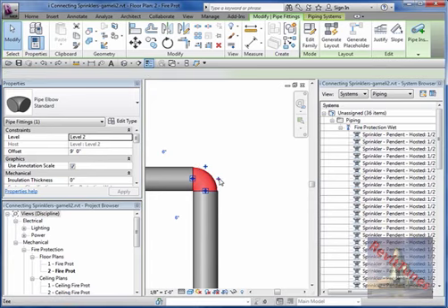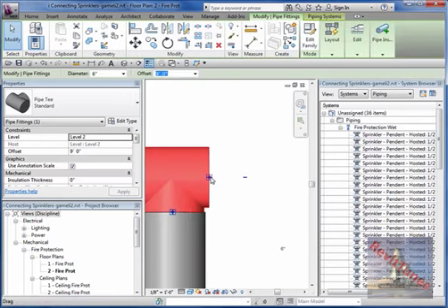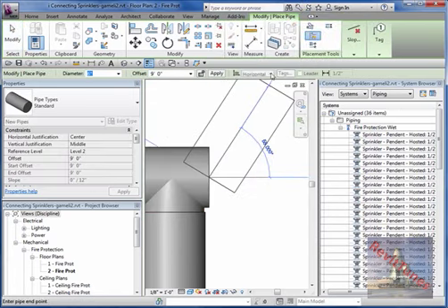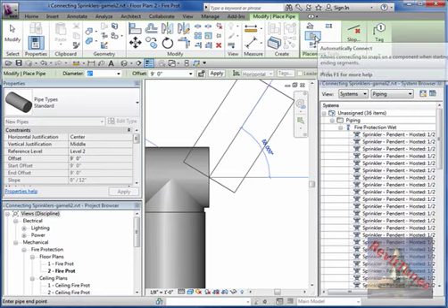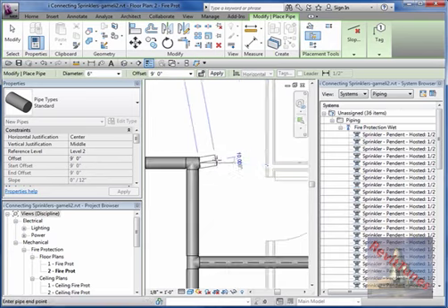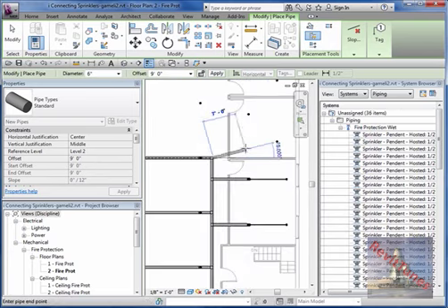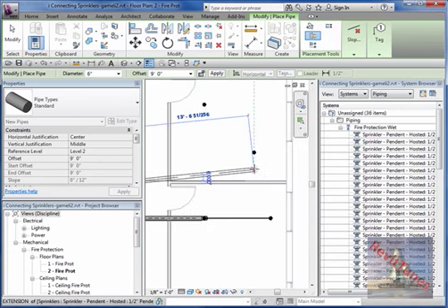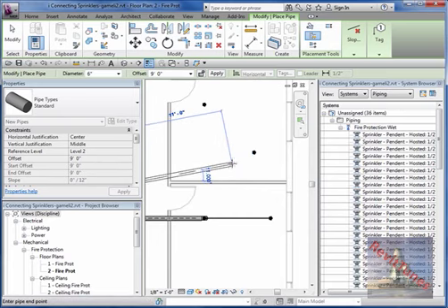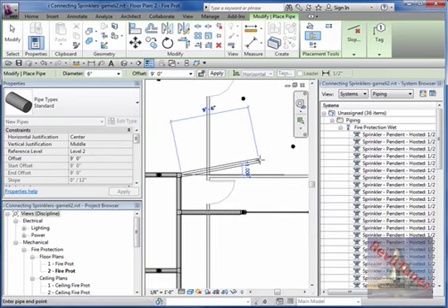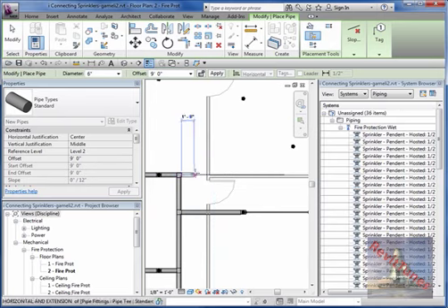And if you click on the plus sign, then select it again, you see now I have a connector here. I right click on the connector, draw a pipe. Notice that this button is highlighted, it's auto connect. Now I'm not clicking, I'm using my wheel to zoom out. Now I'm going to hold, before I hit tab, the big keyboard tab, the long horizontal key, and that will create the possibility to do a line exactly like the one I use as the connector, in height and in diameter. So because I started from this connector, it will be just like these other mains.